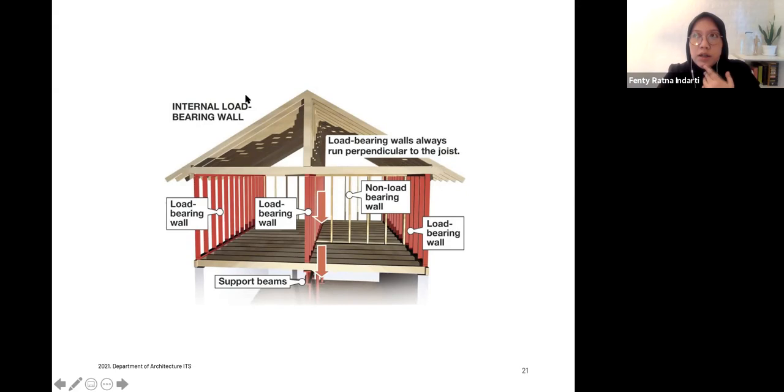There is the internal load, which comes from the weight of the structure, that must be considered, and also the other part of the structure, which is the roof. A non-load bearing wall will not distribute those loads from the upper part. It just has to sustain itself, and then its weight will be added to the other loads in the building.